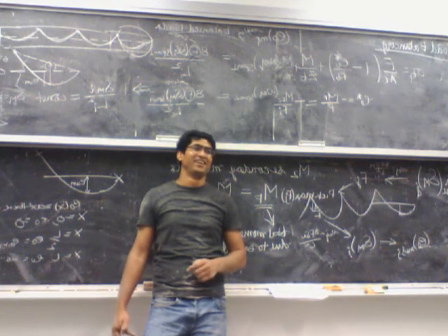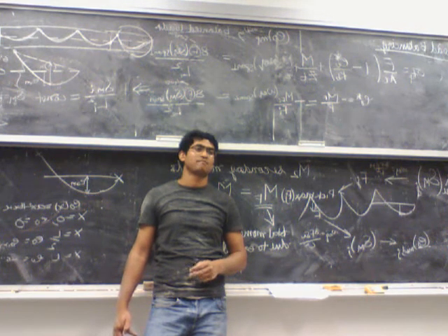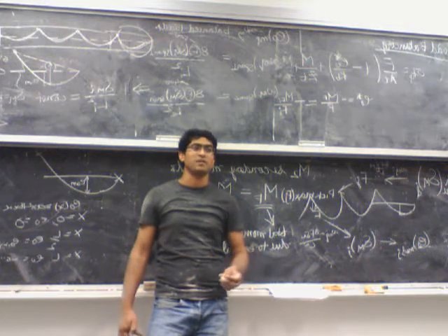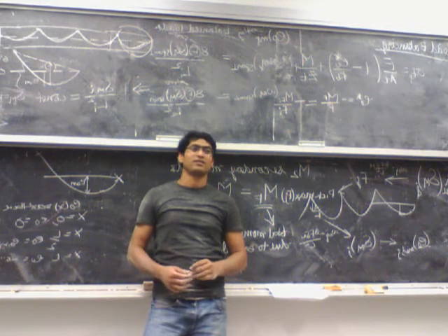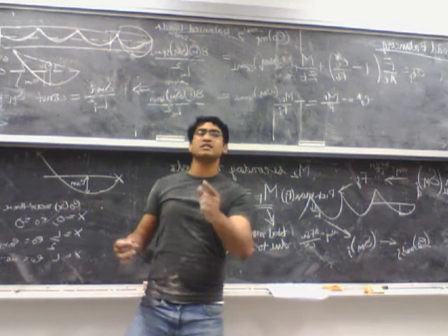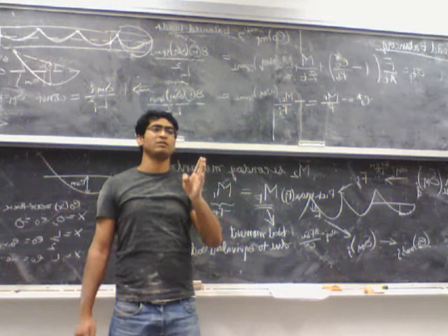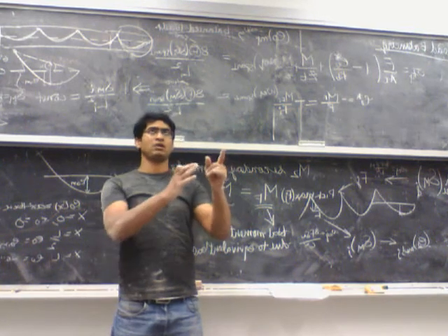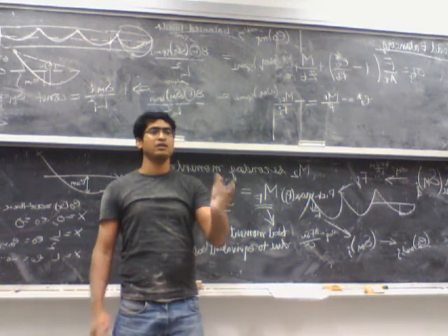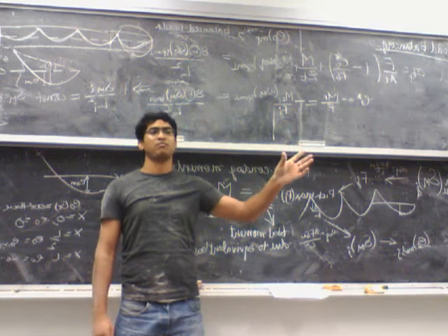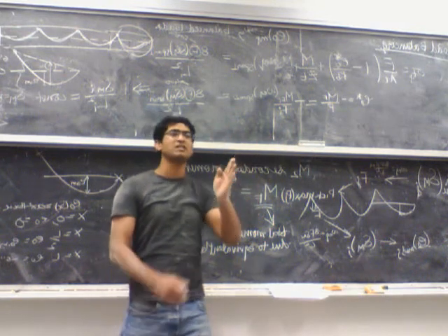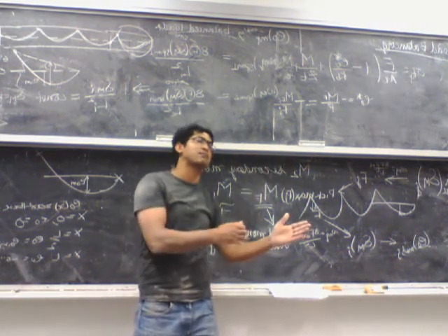Yeah, but if it's less than E naught MP, can't you just... No, it has to be less than E naught MP. Yeah, that's it. No, you need to make this check only for the spans where the tendon profile is not symmetric about the midspan. Yeah, so if you look at the assignment, I didn't even check for the middle span because I know that for the middle span the maximum E naught does occur at the midspan.